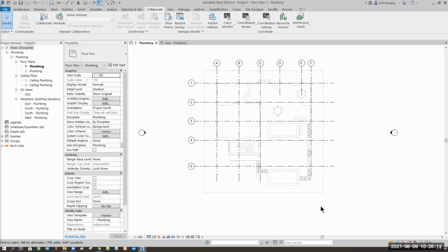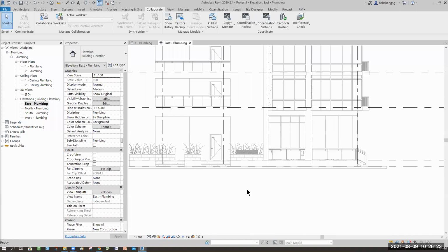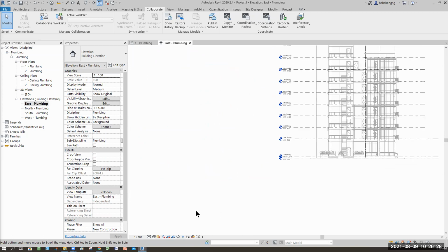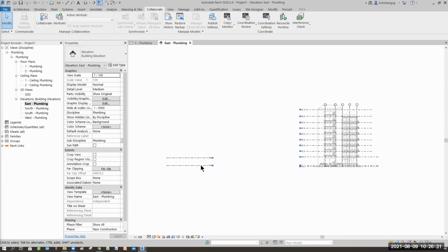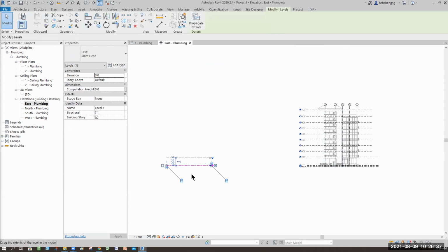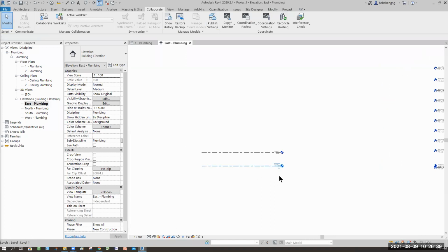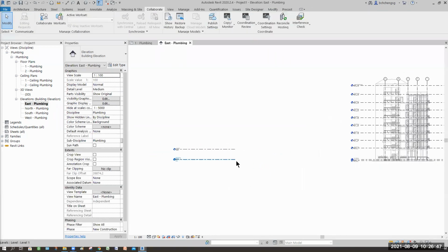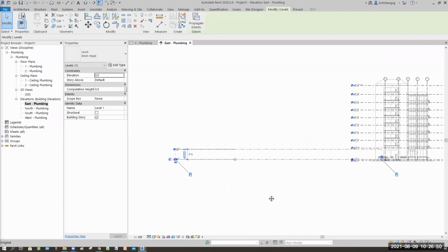Questions? No, sir. If no, then I will proceed. Okay. Now, when it's done, let's go to the level. That means now I go to the east. Now you know that our view has been shifted. So where is our actual level? See, it's here. So this one cannot be moved. Remember, you got to extend this over. But before that, try to toggle the orientation. Right? So I'll drag this across.